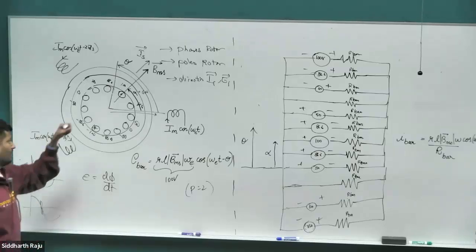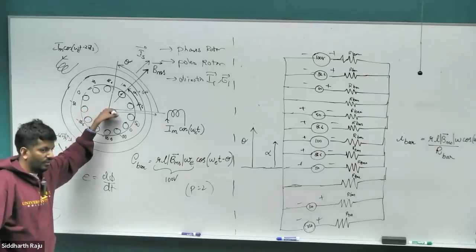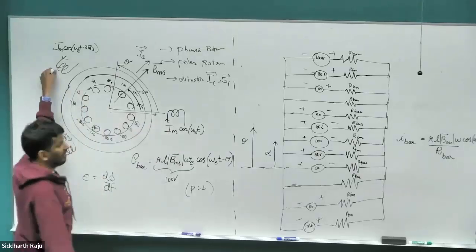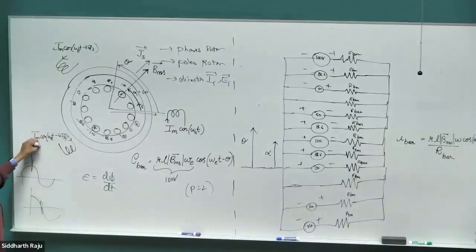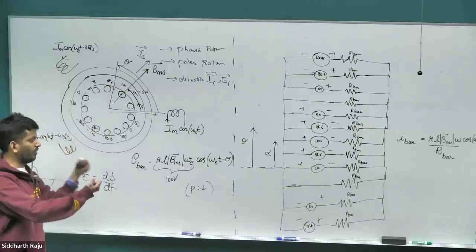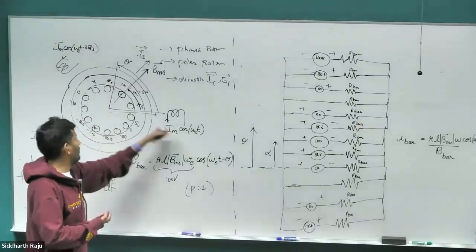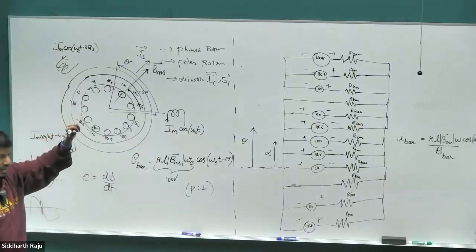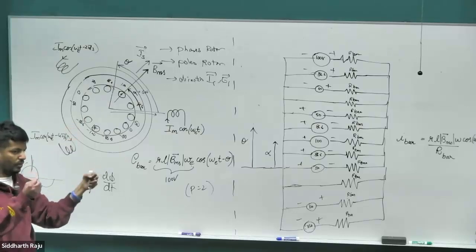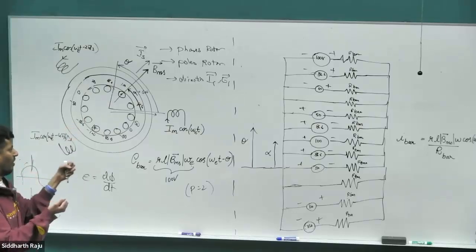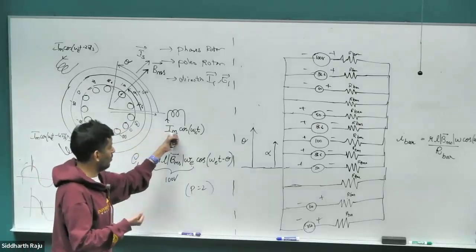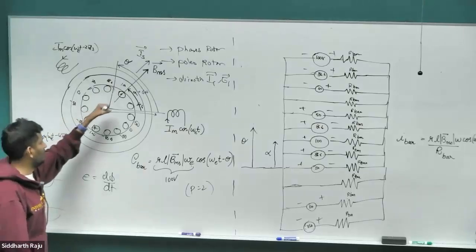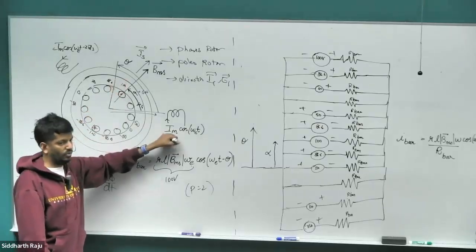So the space vectors have nothing to do with the actual currents themselves. Right? Even in the case when we had stator current space vectors, all the three currents were real entities. None of them have an imaginary component to it. What we are doing is putting it into a transformation that's basically saying that if the sum of these three currents is zero, which is the case for a three-wire system, then all of these points lie on a plane. And the space vector transformation is merely a rotational transformation. Right? It's just a shorthand notation. The e to the j theta is just a shorthand notation for doing the rotational transformation. So that is what is introducing the complex entity to the space vector. It has nothing to do with the actual currents themselves.